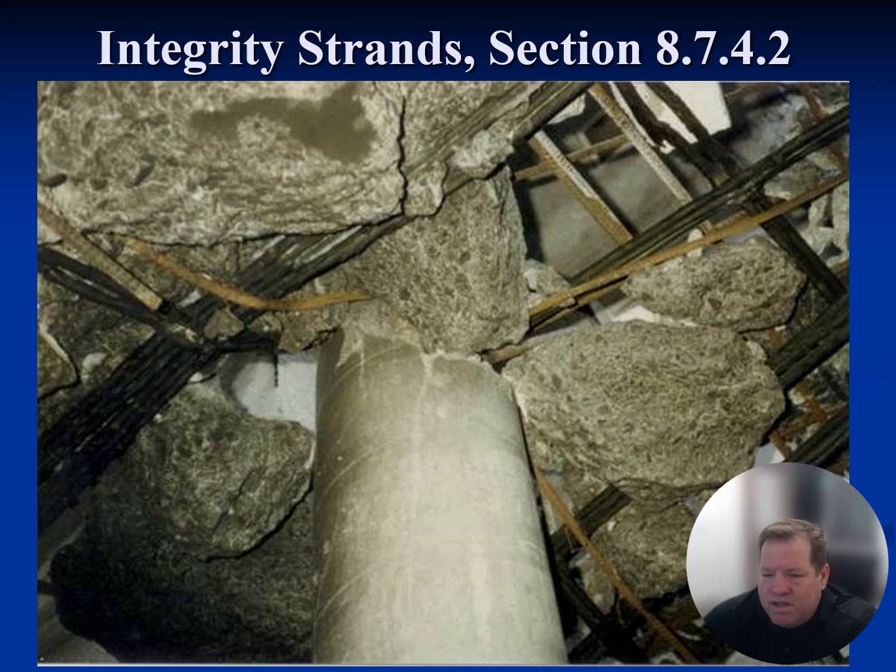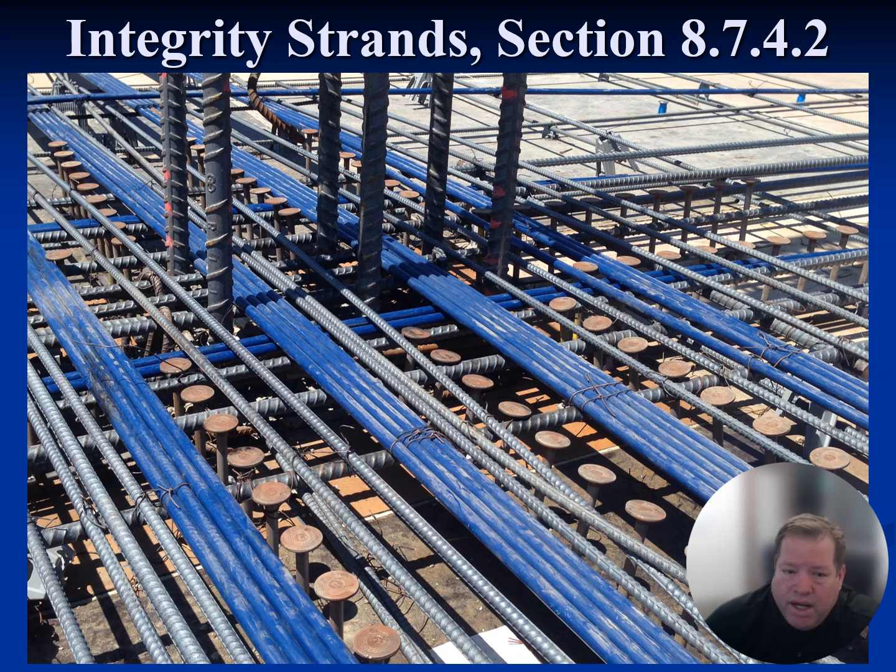They're nothing more than something to hang your clothes off of. Since the tendons are unbonded and they don't need the concrete for strains, for stresses and stuff like that, the post-tensioning that's embedded in these columns is the only thing holding it up. So in that sense, the integrity strands in the past photograph are what held that structure up. So that's really very, very important.